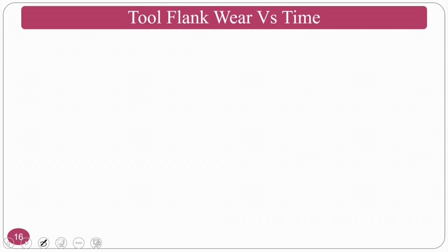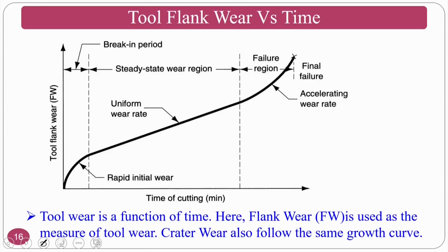Okay. So, now we will see the flank wear versus time, how the flank wear progressively increases with respect to time and all those things. Okay. So, if you see this one, the time of cutting versus the tool flank wear, normally a similar trend the crater wear also follows. So, I am just touching about only the flank wear. I will also explain you why I am touching only the flank wear, because the flank wear is the criteria that people can easily measure, but the main reason is the tool life criteria basically takes from the flank wear only. So, that is the main reason. Whenever that point comes, I will explain you.